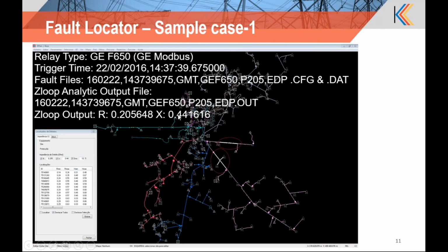The loop value, R and X, are transmitted over 104, and SCADA analyzes it with the GIS map, and you can indicate the location. From the feeder, these two are the possible locations with respect to the error permitted. They calculate on the location, and these are the probable locations of the fault. So two locations have been indicated based upon the distance from the outgoing feeder.